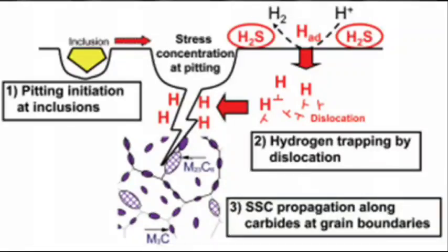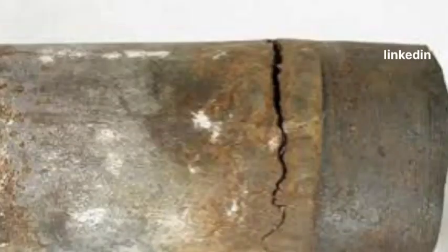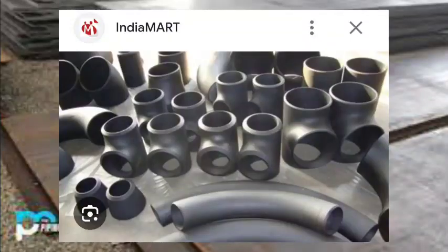Very good question, sir. I thank you for that question, because the answer may help others also. There are two criteria. When you have carbon steel in a sour environment containing H2S and water, you have two types of damage mechanism: sulfide stress cracking and hydrogen induced cracking. For sulfide stress cracking, the material shall be NACE certified. If your material is NACE certified, then automatically it is resistant to sulfide stress cracking. Hydrogen induced cracking is addressed for plates via testing, and for pipes and forgings, as I discussed, via sulfur control.